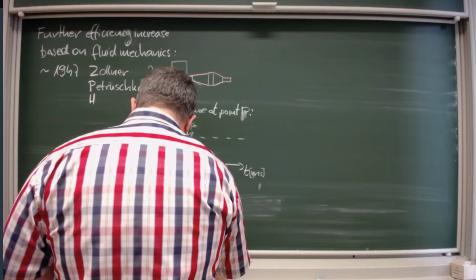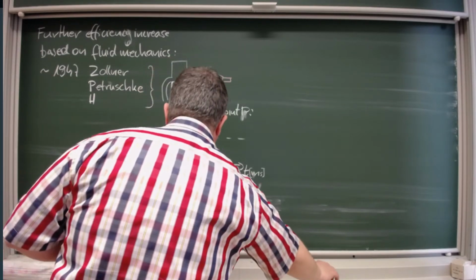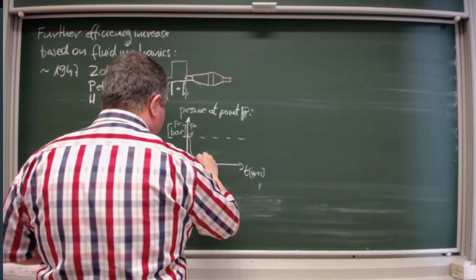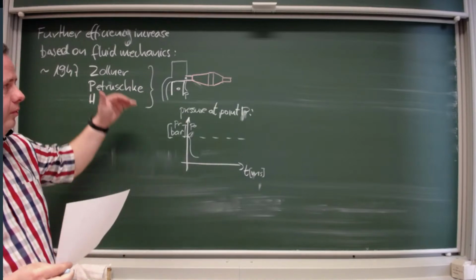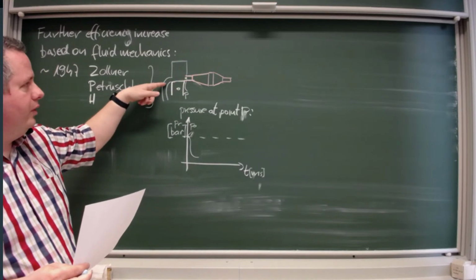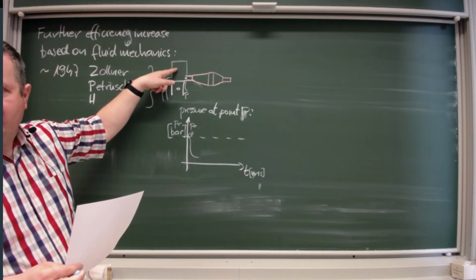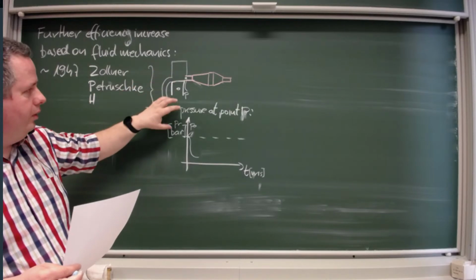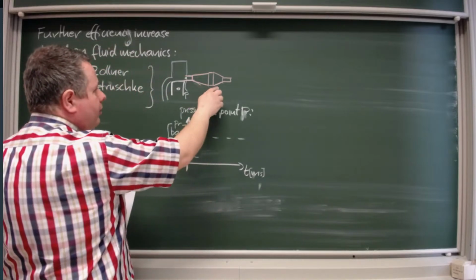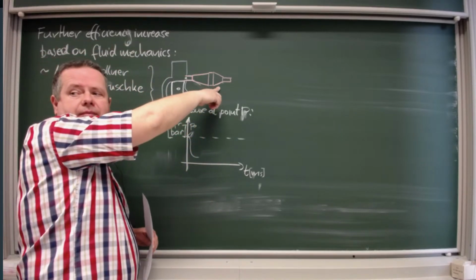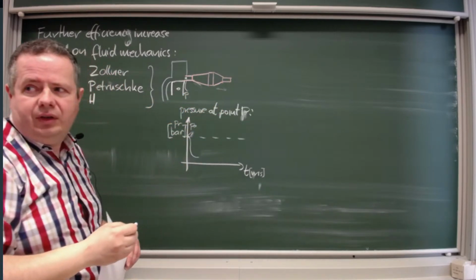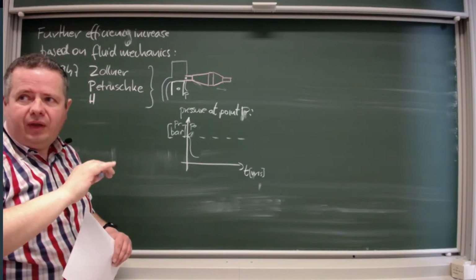At the start of the opening, there's a sudden decrease that helps the evacuation of the burned gases. And the evacuation of burned gases helps the entering of the gas from the crankcase chamber. And after a certain time, by the time the gas flow reaches the confuser, though the gas continues going out, the pressure behaves strangely.